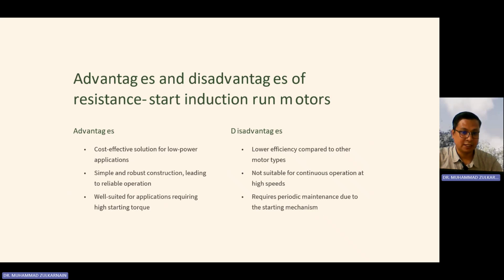For the disadvantages, the first is lower efficiency compared to other motor types, the second is not suitable for continuous operation and high speed, and the last is that it requires periodic maintenance due to the starting mechanism. So this is not suitable for long-term use in a running motor.